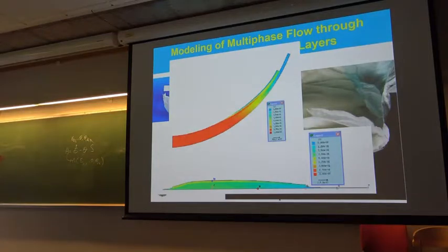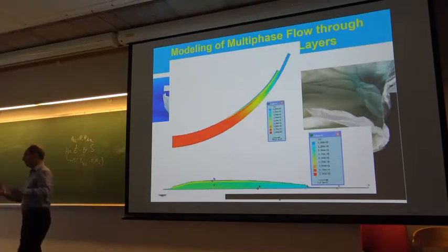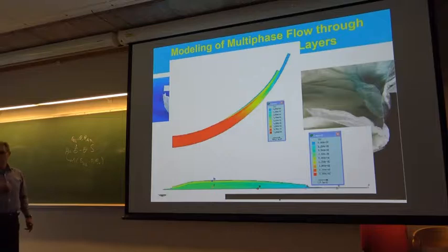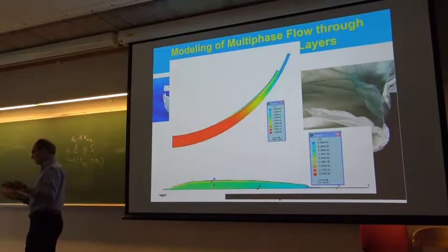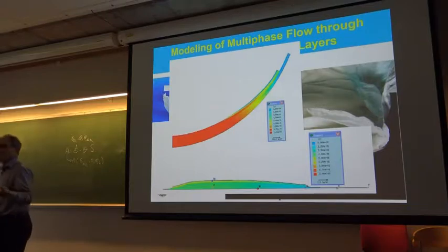And then there is a whole literature on modeling them, looking at the moisture distribution through them. This is one example that we have done a lot of ourselves, where we measure capillary pressure. It's basically the same sort of modeling as you do for an oil reservoir. For samples, we determine capillary pressure saturation curves. Then we fit the Van Genuchten formula or Brooks-Corey formula to it. From there, we can also get relative permeability. As far as I know, there are no measurements of relative permeability done for them. The saturated permeability is measured, and then Richards' equation is used to simulate it.